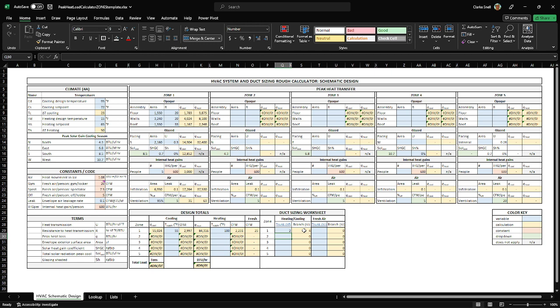So they're going to have more surface area per duct, which means more friction. So this is just a rule of thumb. I just went times 1.7, based on the changes happening between trunk and branches in the book chart. That's all I did.